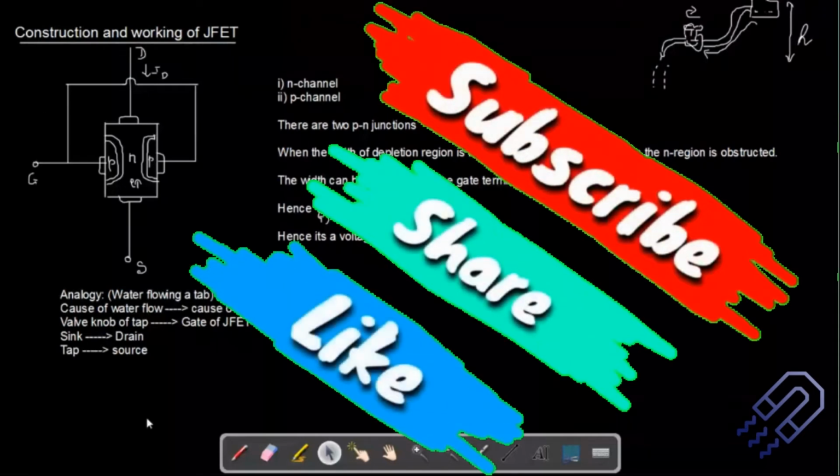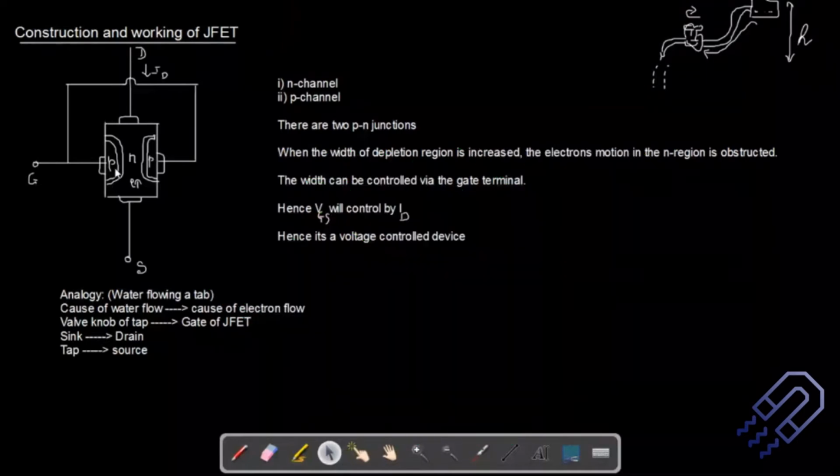Okay, next we are going to look into something which is very interesting. The point here is that this depletion region that we have here basically will keep on reducing in size as we go from up to down. So it will be thicker here, the depletion region, and as we go towards the bottom, the depletion region will become thinner.